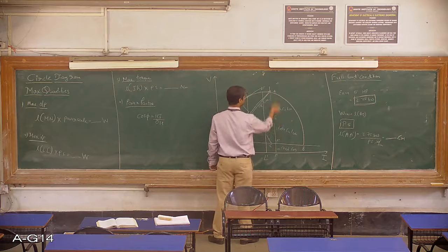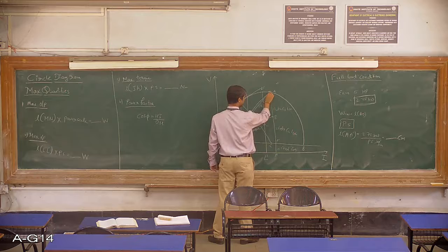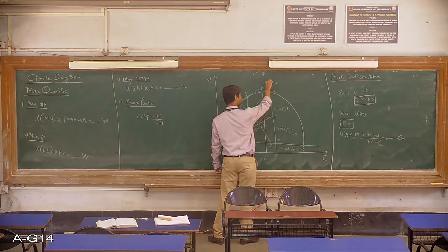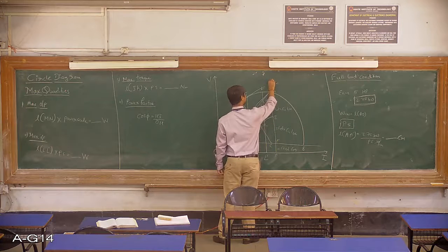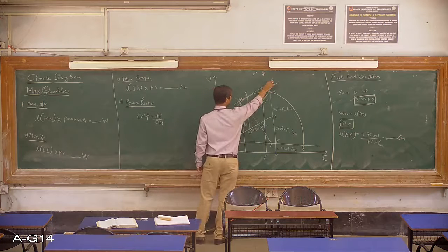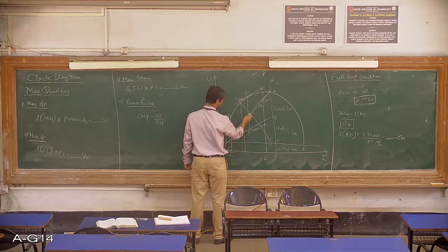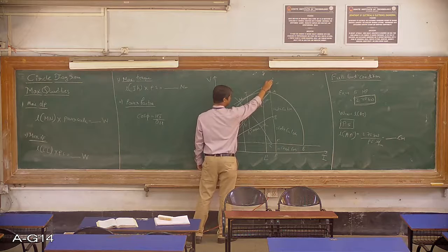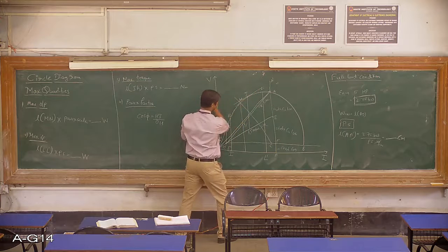So for the same length, we are going to extend the line, this vertical line, from the point A. Now suppose that is around 2 or 3 centimeters. For those many centimeters, we are going to extend the line. Okay. Now let me name this point as A dash. Now what to do here is, from the point A dash, draw a parallel line to the output line towards the y-axis. Okay, so draw a line parallel to this output line towards the y-axis.